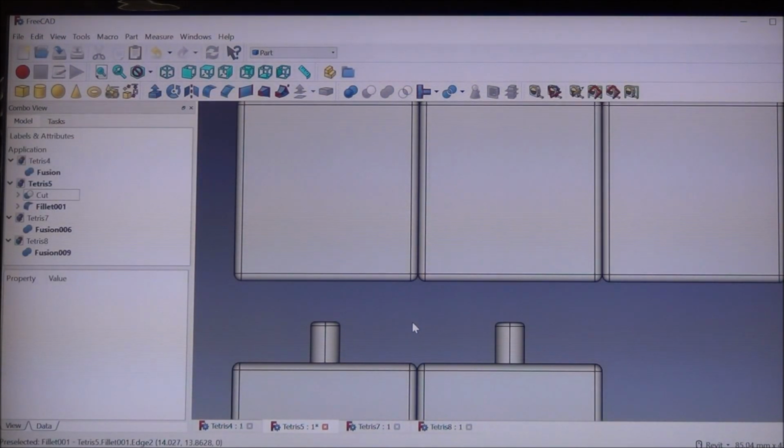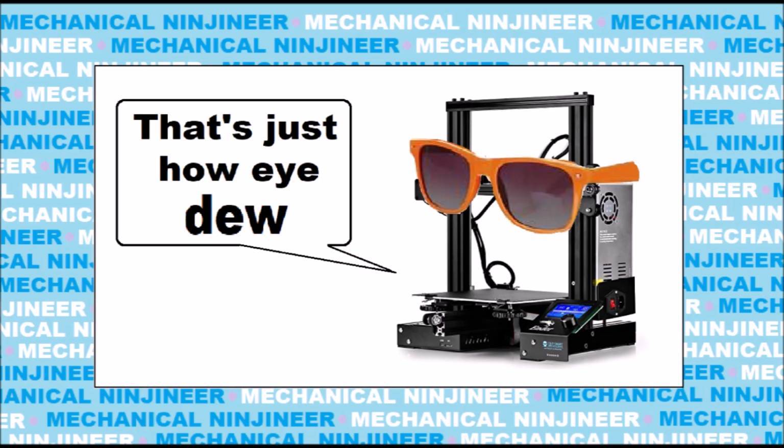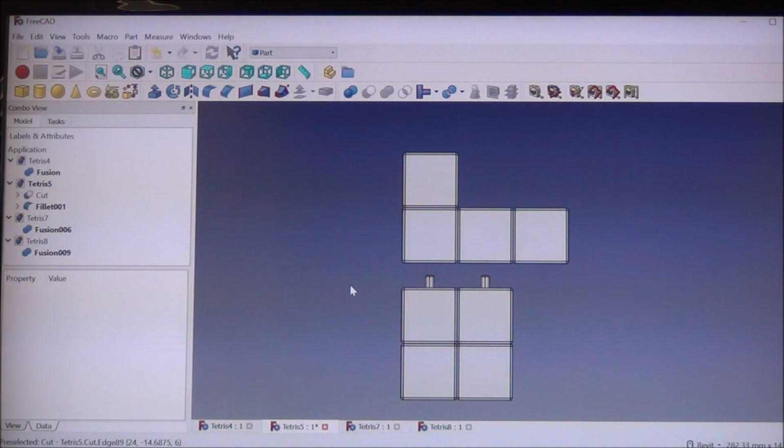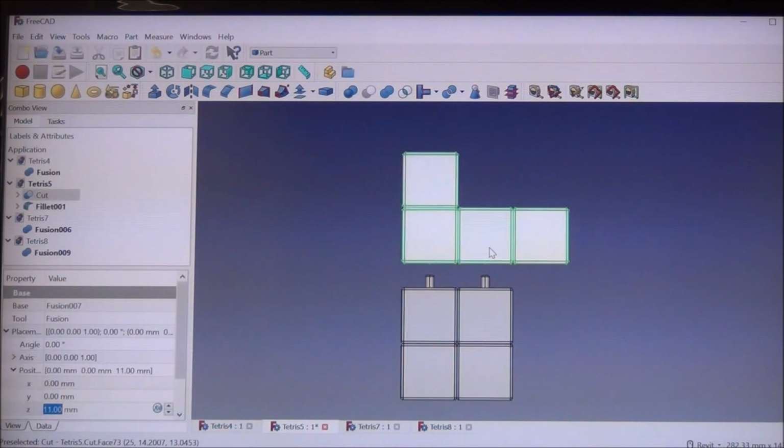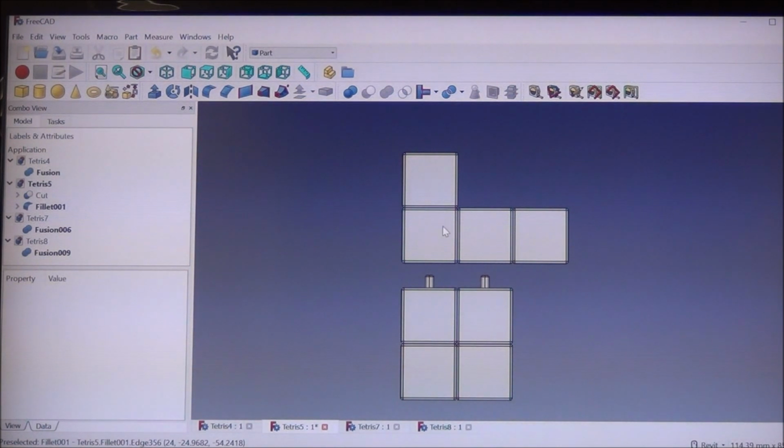Wonderful. Now, in case you haven't already figured it out, the reason why we had to make the cutouts slightly larger than the pins themselves is so it'll all fit together appropriately. If we made the pins and the holes the exact same size, believe it or not, it wouldn't actually fit together simply because of how the 3D printer prints. I sure hope that made sense, but if it didn't, don't sweat it, it will in a few minutes. And so with that, these two pieces are done and ready to be put together.